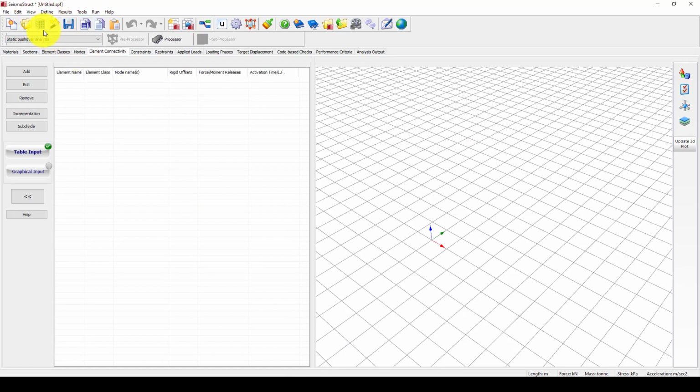So the program becomes heavier because it has more than 4,000 steps. It's nonlinear, and nonlinear time history is quite an expensive analysis. It takes lots of memory and also graphics of your computer. So now let's see the post processing, which will show the deformation with convergence data. You can see here the estimated size of the output file is more than 7 GB, so it's quite large, and 7 GB of data is loading in the program, so it's taking some time.